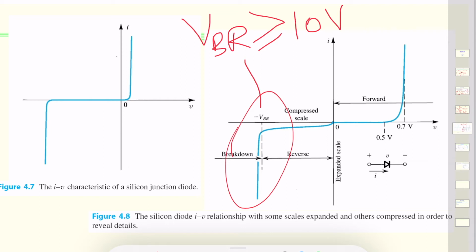It's a common form of reverse breakdown when we have to withstand a high reverse voltage without any appreciable current. Once we get into avalanche breakdown, the large reverse current at the high breakdown voltage results in very high power dissipation.